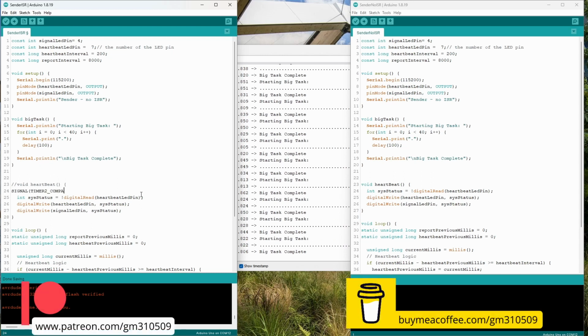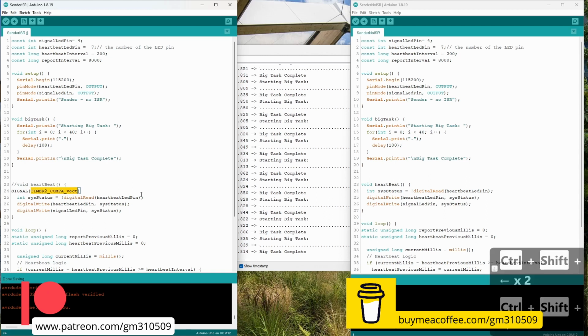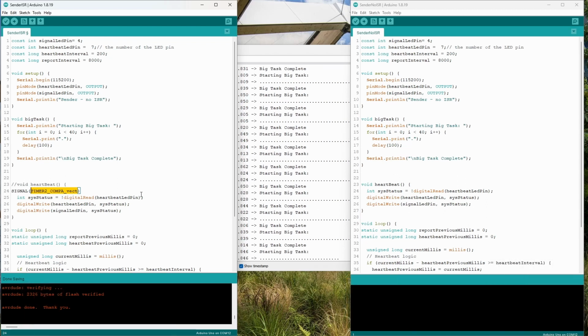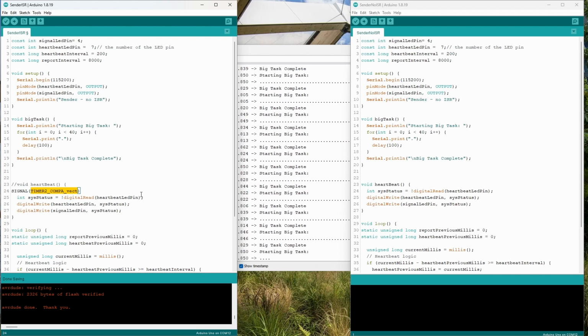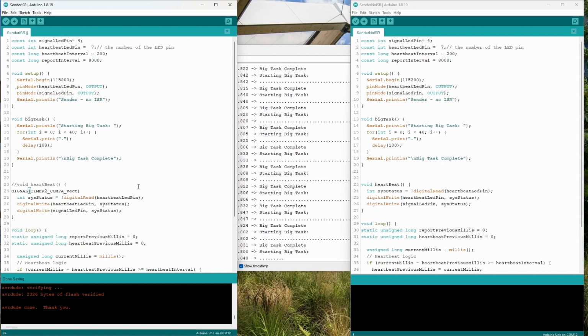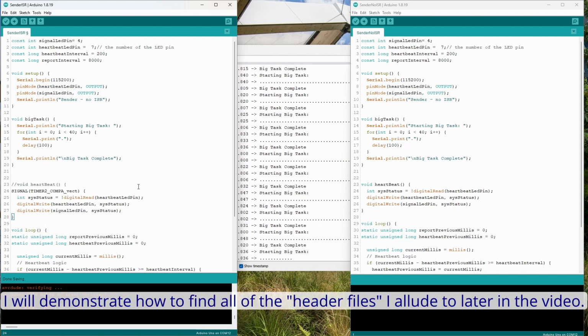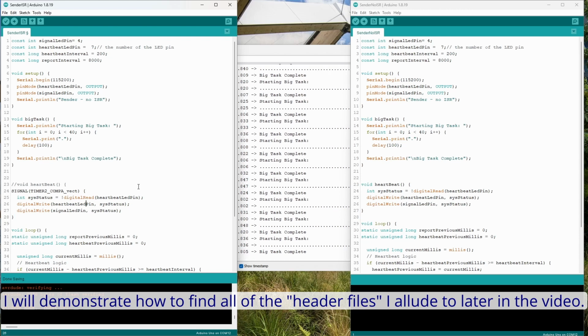So where do you get these from? It's a little bit challenging. I've never really found a definitive list other than the source code for, in this case, the ATmega328P include file, which is included when you compile it. How do you find those things? Usually you just have to look for an example that references them. There are header files included in the compiler that define them for you. But I usually found you can work them out from the data sheet, or you have to find an example. So that's the one that we want for our systems.